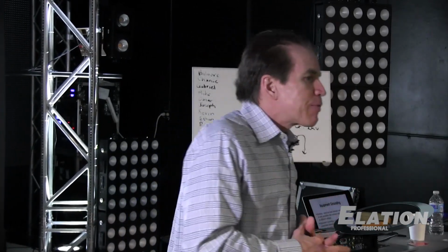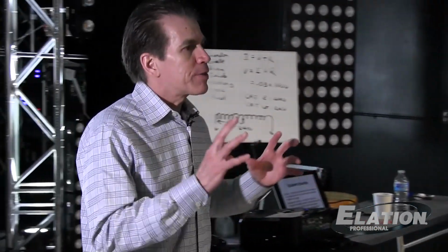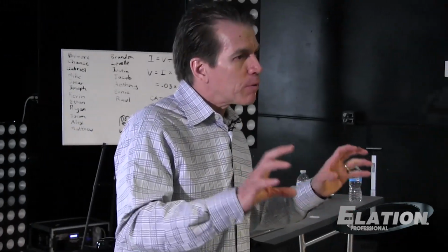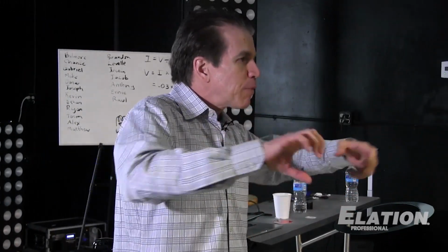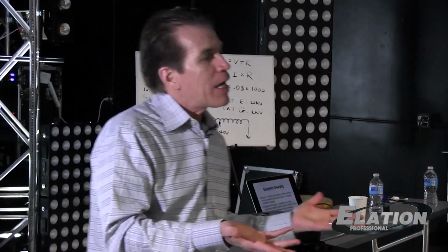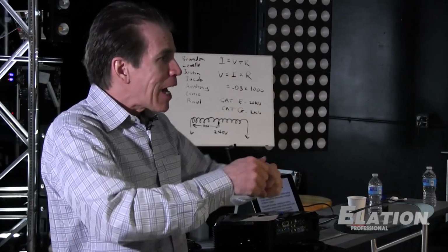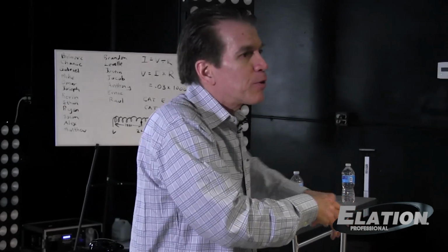A lot of times, not a lot of times, but occasionally you have to take some wire and some clamps or some connectors, and you have to bond things together. So for example, if you're building a stage that's on scaffolding, that metal scaffolding should be bonded to the electrical system if you're going to feed electrical to the stage. And they make C-clamps that connect to a green grounding conductor that connects to the portable power generator.